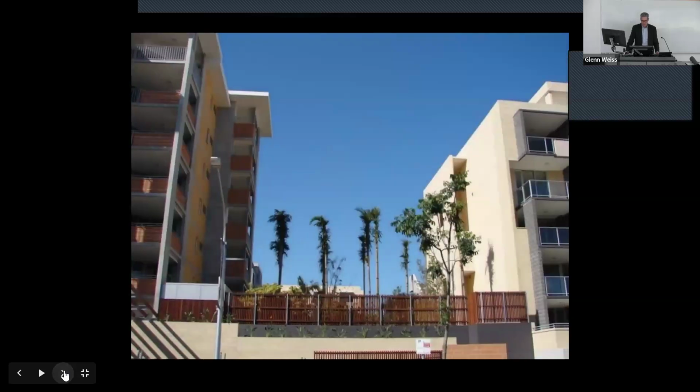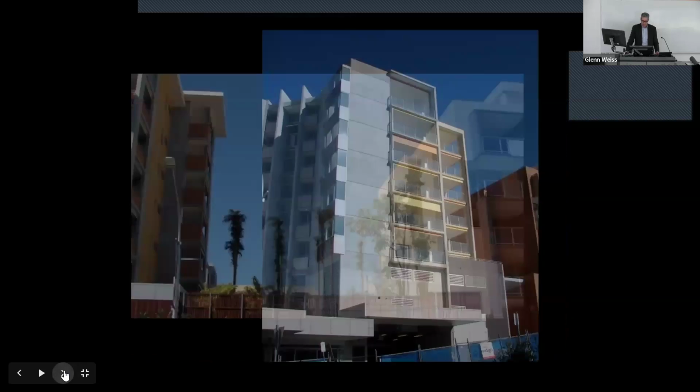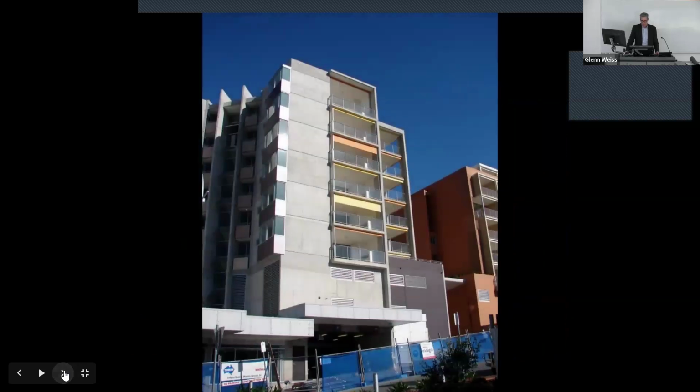So here you are, making the space in between, putting trees within that space. Hopefully those little pathetic palms will fill out over time, to let the air flow into the center space and also to cool that air down a little bit. You can see again these multiple blocks, also doing that trick on the corner where the balconies are open on both sides, so the air moves through that, and that probably makes those spaces very comfortable to sit out in on the balcony.